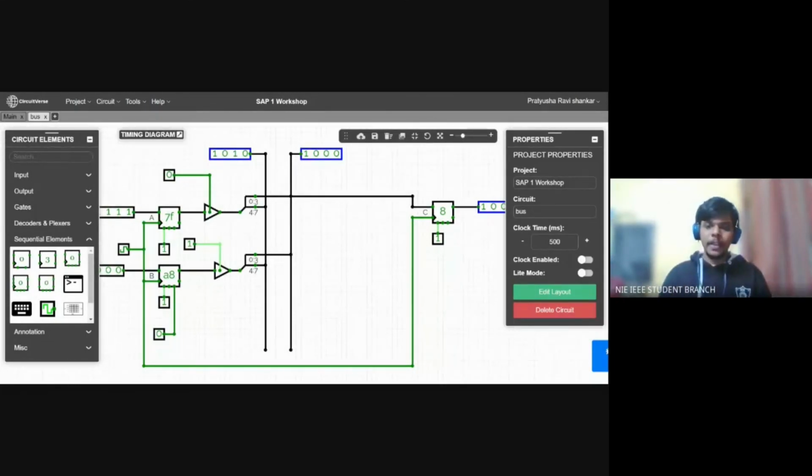So if you don't have that high impedance state in the bus, unintentionally all the bits that are set to 0, current will be simply flowing into the circuit, which you don't want happening. If you want to completely isolate something from a wire, you just use a tri-state. When you disable it, nothing flows between those two connections. Current doesn't flow in, current doesn't flow out. So that's just a quick fact about tri-states.